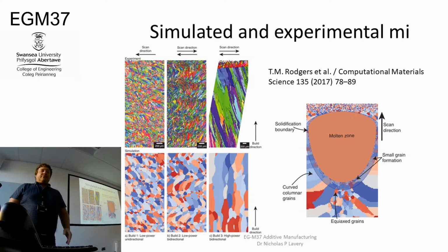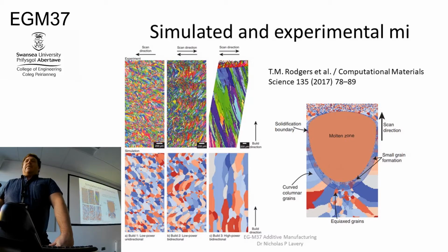So all of those things I've told you about today are important for additive, and you've got to try to take all of those into account to a little extent, or know a little bit about them. Anything that affects the melt pool, the width, the depth, the length, will ultimately affect how each single track is formed.